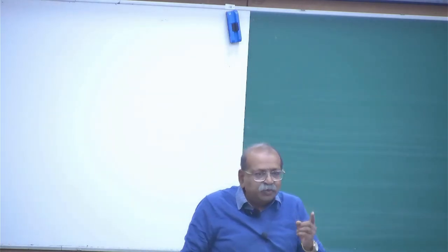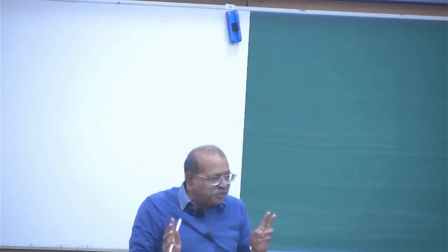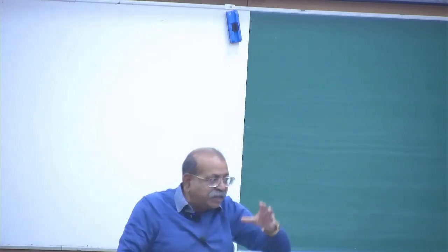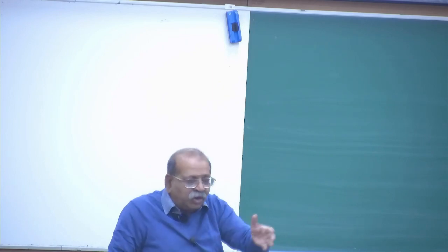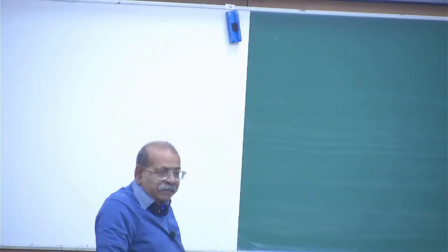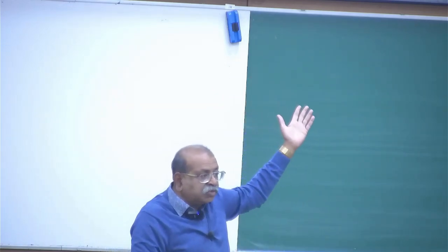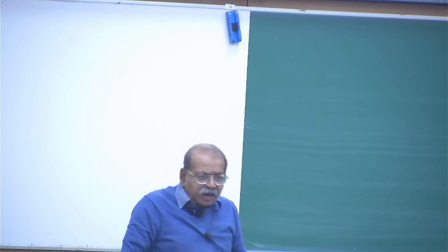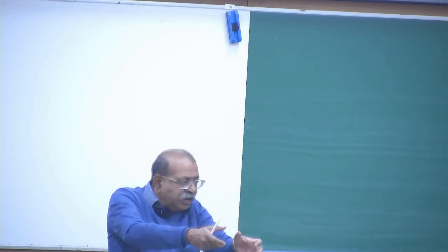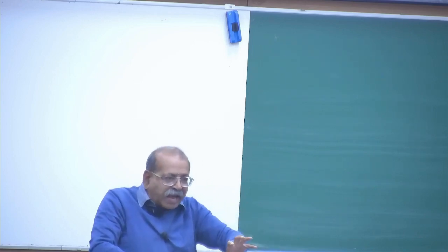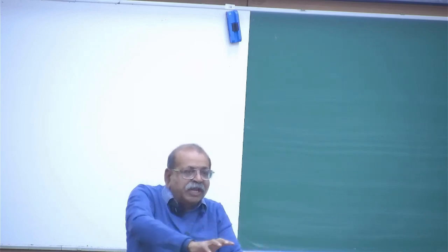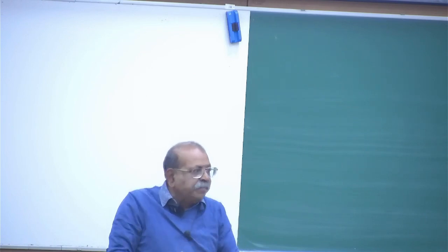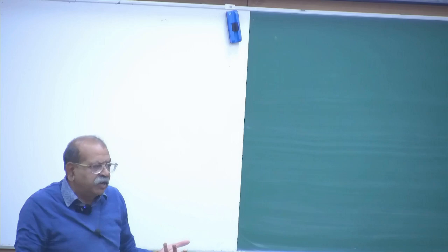So we need basically two things: given there is a torque T0 on the rod AB, how much torque is transmitted to rod CD? And also, what is the relation between them: if B rotates by an angle phi B, how much will C rotate at the same point? And then we have to use our relations. Okay?